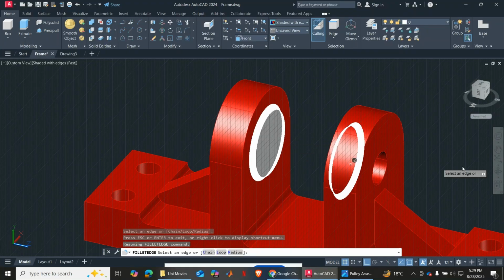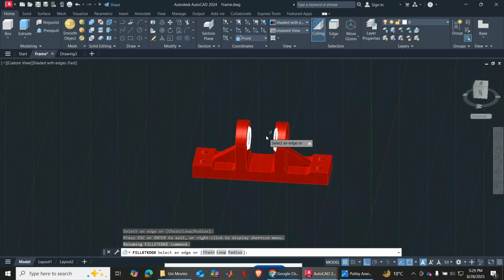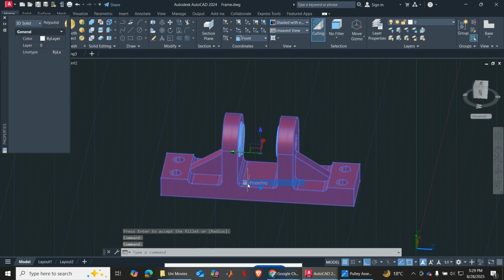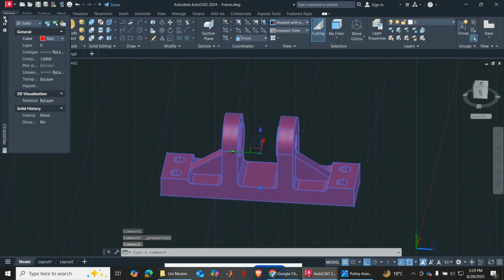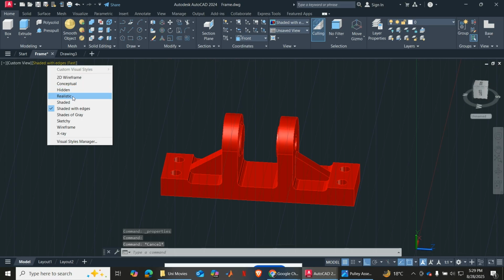So as you proceed, so you click rotate, and then after you select, you escape. So to proceed with action, enter. Okay, again I can give it color now so that it's uniform color, red. Close, escape.